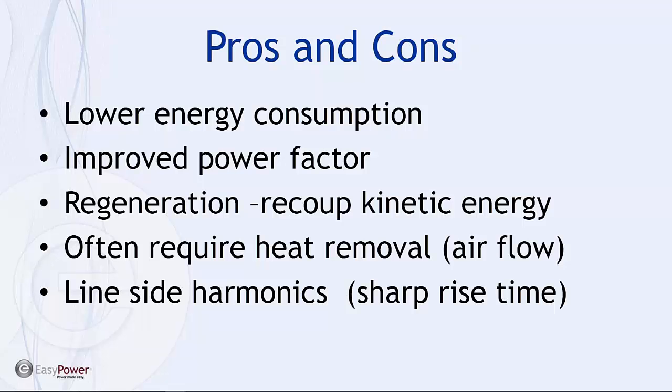It also improves the power factor, specifically the offset angle between the voltage and the current, if you disregard the rise time issues. And then there's regeneration, the potential for recouping the kinetic energy of the motor if we push energy back to the line side of the controller.